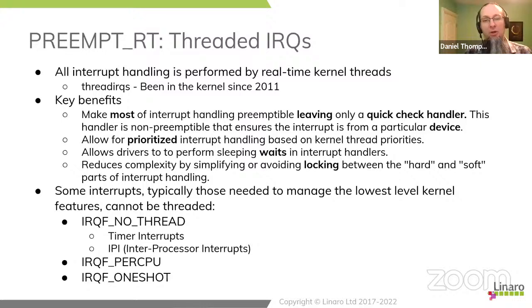More than that, we can mix together interrupts and other activities. So a classic example from audio workstations is you set your audio interrupts to be the highest priority in the system. You then put some of the DSP that is attached to the audio processing at the next level in the system. And after that, you have the rest of the interrupts in the system. That's a very unique thing for professional audio workstations, but you can have tasks that sit at higher priorities than interrupts using this mechanism.